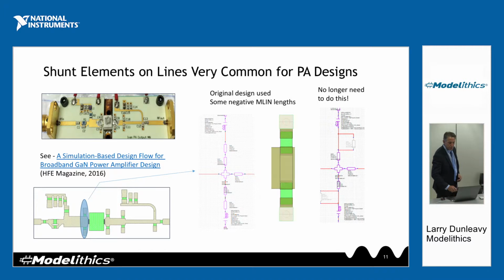This is a design that we presented a couple years ago at this conference, and it's been in an app note and so on. And again, Yvonne likes to use these parts right on the microstrip line and not have a pad. So what he had done in that simulation, which got really good results, was use a negative transmission line to adjust for the reference planes of these pads. With the new models, you don't have to do that anymore.